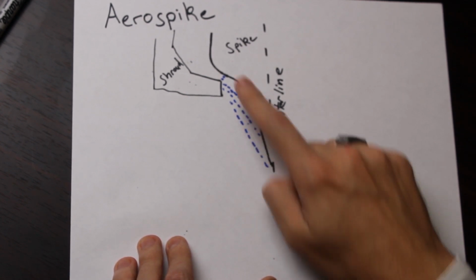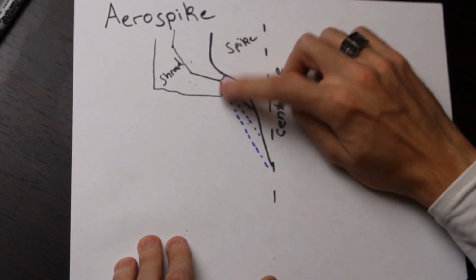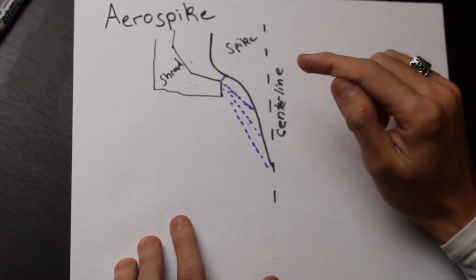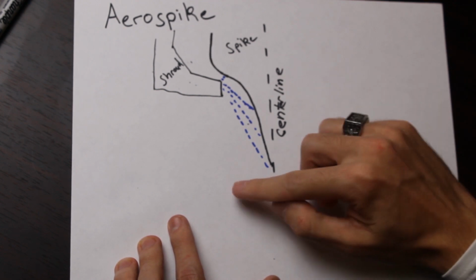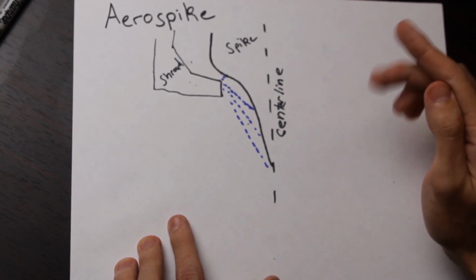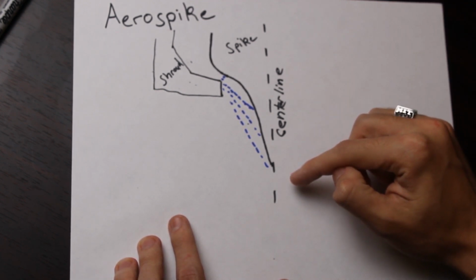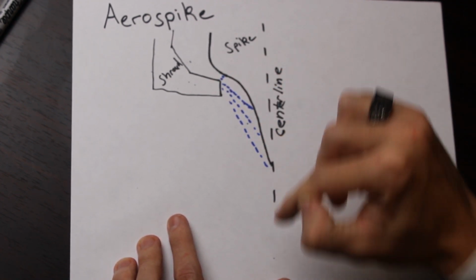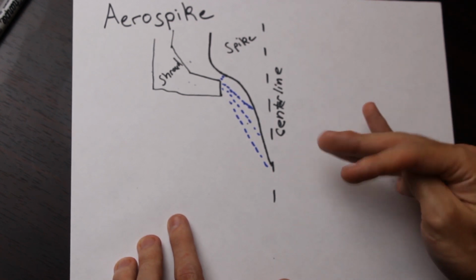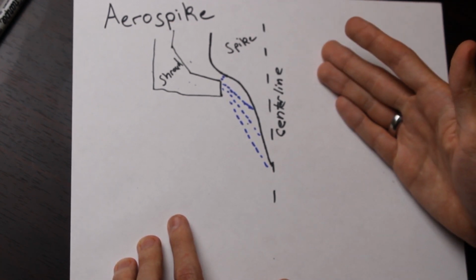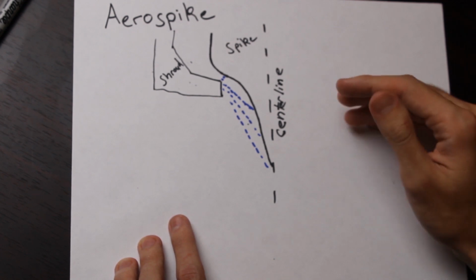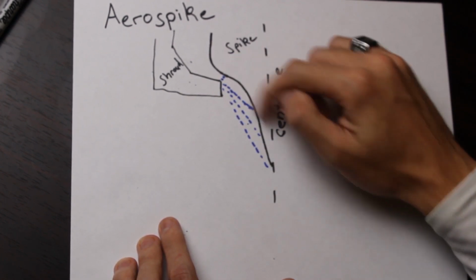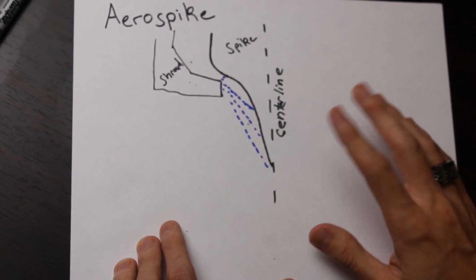All right, so remember we were talking about how the gas goes supersonic at the throat, so Mach 1 at the throat right here. And then normally what you would do, if you were designing a bell nozzle, is you would pick what Mach number you wanted the exit to be at, and then you would space these lines equidistantly to reach that Mach number. So let's say you wanted to draw 10 lines, you go from Mach 1 to Mach 5, then you have a line every 0.4 Mach, because you can figure out what the area needs to be to draw that line to.